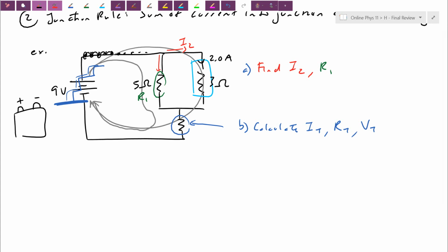We're going to use Ohm's law, which is a very simple rule, but just be careful when you use Ohm's law: which part are you looking at? So let's do Ohm's law right here. V is equal to IR. I have the current, which is 2 amps, and I know that the resistor here is 3. My Ohm's law says I'm using up 6 volts here. Right? So I figured out 6 volts.